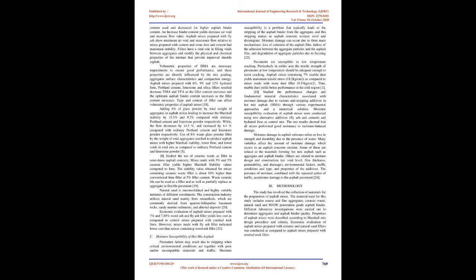B. Effects of filler on hot mix asphalt. Optimum asphalt binder content can be affected by the type of aggregate, asphalt binder, mix design and filler material. It was observed that the mixes prepared with fly ash as filler exhibit marginally inferior properties compared to cement and stone dust control mixes. The use of fly ash as filler material in asphalt mixes not only reduces the cost of execution but also partly solves the fly ash utilization and disposal problems.